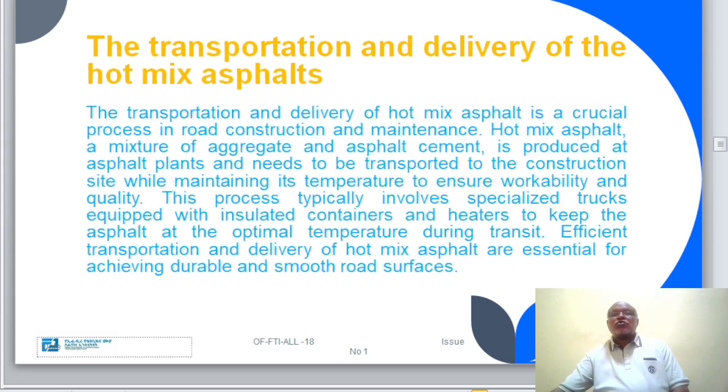Let's see transportation. The transportation and delivery of the hot mix asphalt from the plant to the paver are carried out with haul trucks, which should be insulated and sheeted to prevent heat loss and to protect the hot asphalt from bad weather conditions, especially rain, winds, and low air temperature.